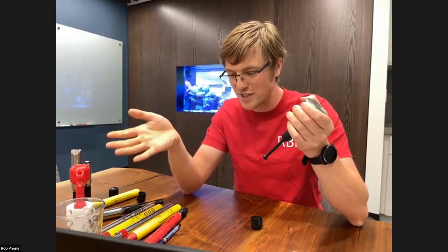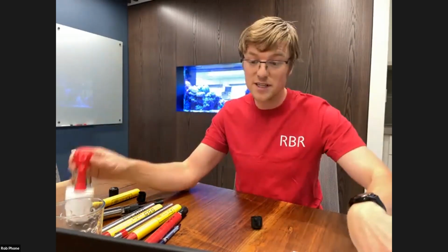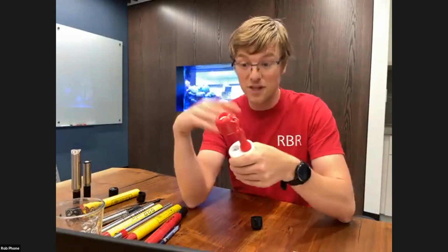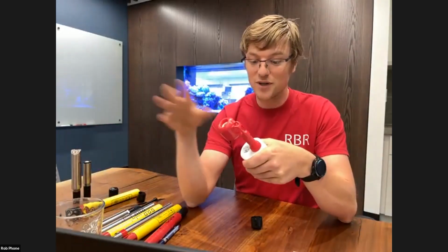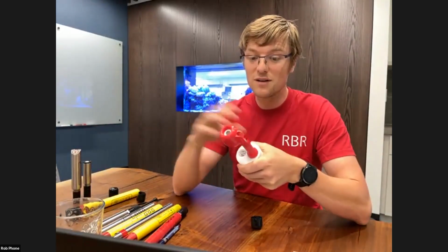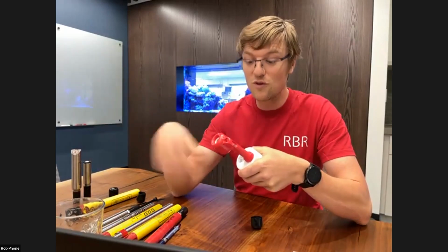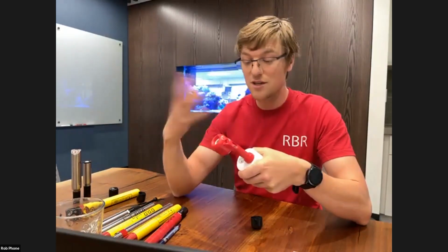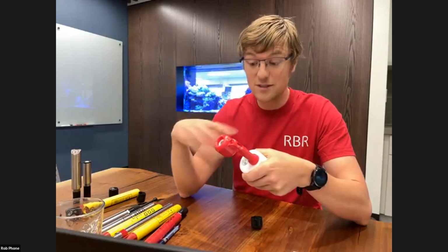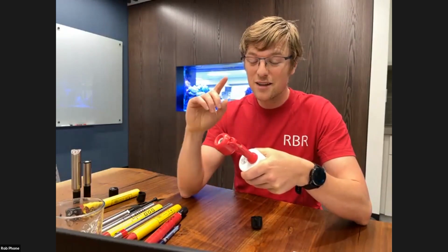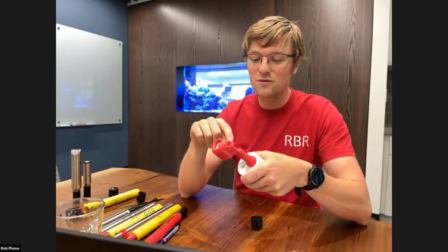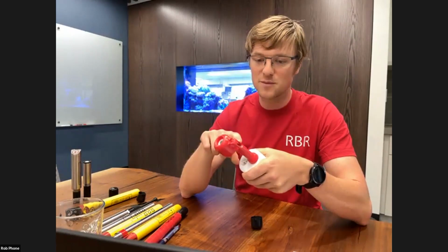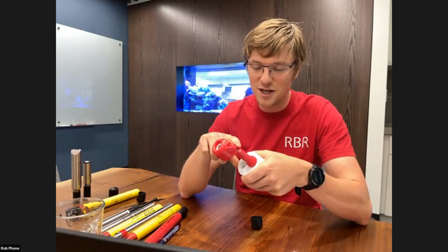So if you're working with a CTD, the conductivity sensor, it's a flushing action. So, you know, it can sample up to 32 hertz as well. So as the volume of measurement is being flushed, it's responding almost instantaneously. The parameter you'd want to look for is the time response of the thermistor. So this has a 100 millisecond time constant.